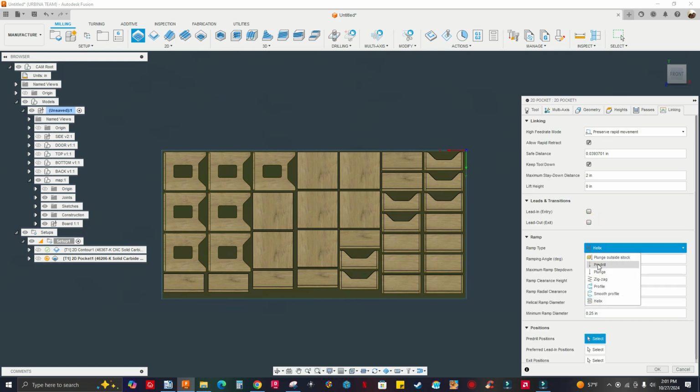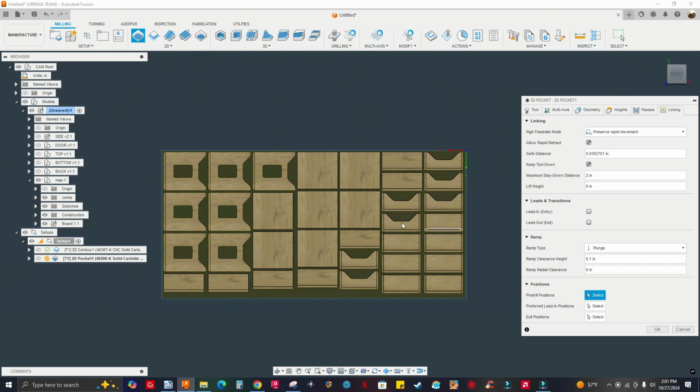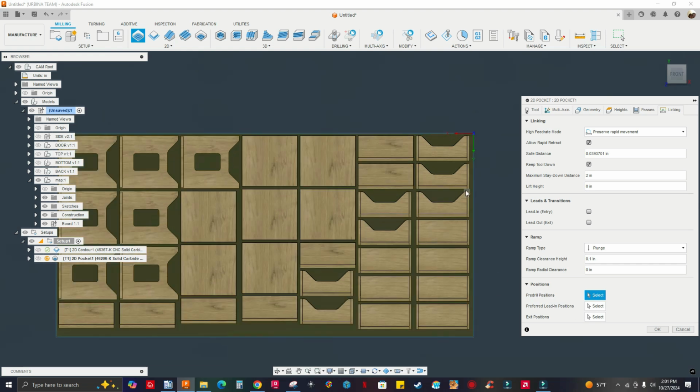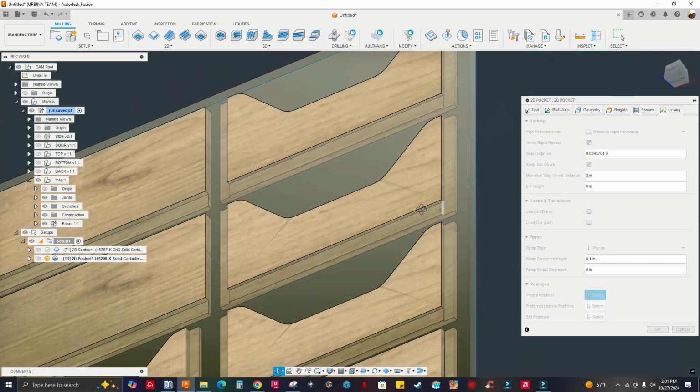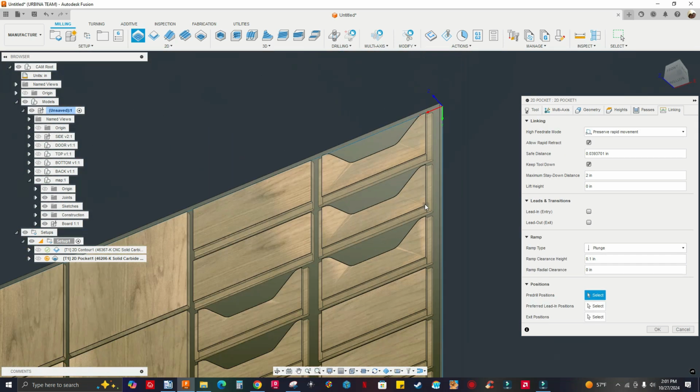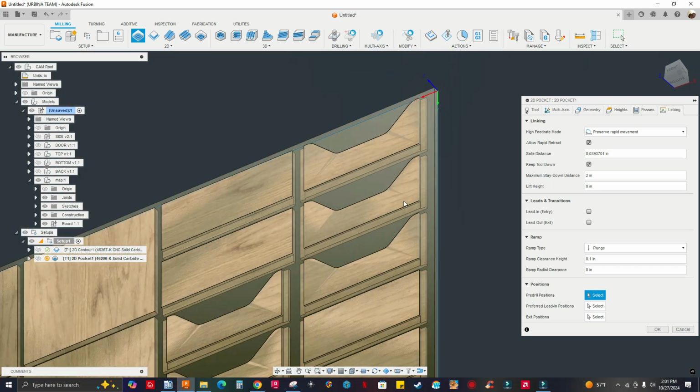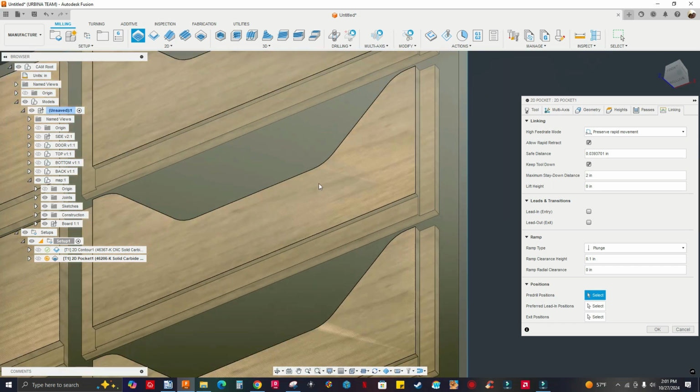That's okay. That tool's not gonna wear out quick. The tip is not gonna break anyways. I'm not machining too deep. I think the deepest one is like 3/16. Actually, it's a quarter inch. Deepest one right there. It's a quarter inch. All right, that's fine. So I'm good. I'm gonna click OK.